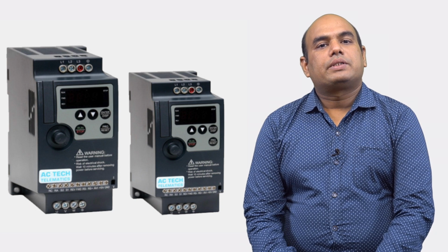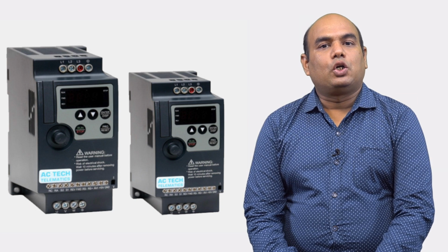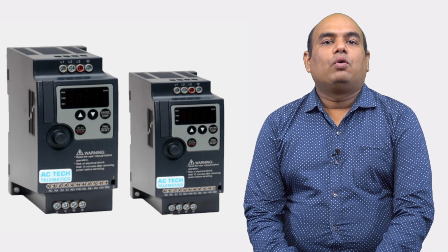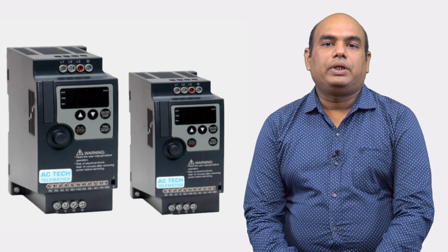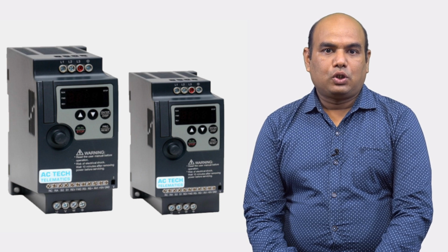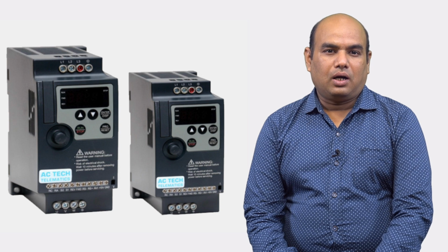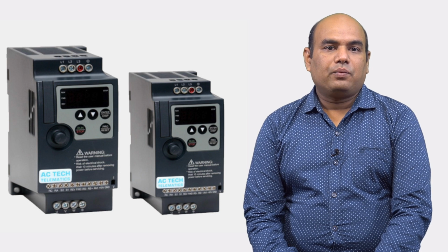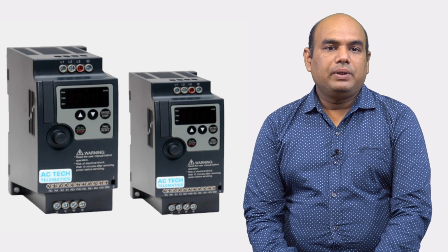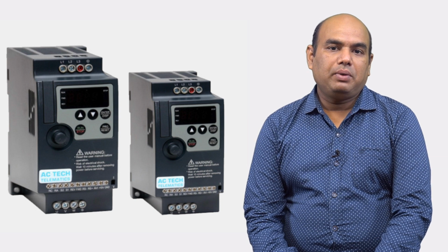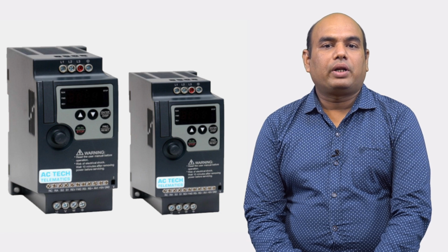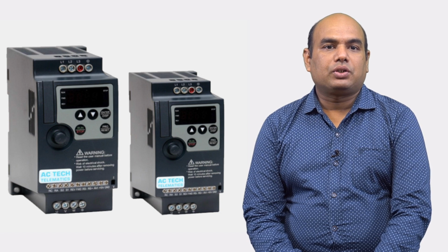The curve suggests the speed control and the braking operation are available from nearly zero speed to above synchronous speed. A given torque is obtained with a lower current when the operation at any frequency is limited between the synchronous speed and the maximum torque point, both for motoring and braking operation.